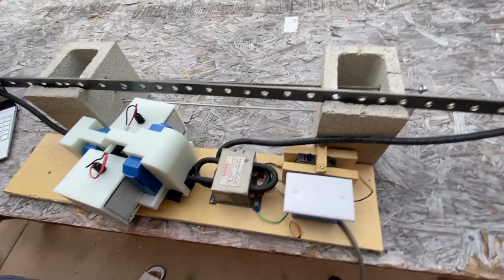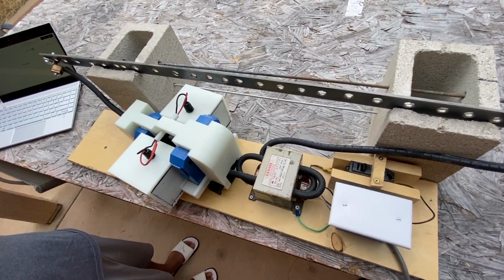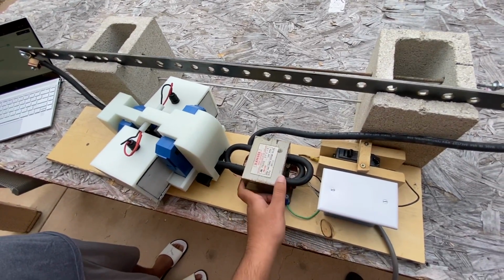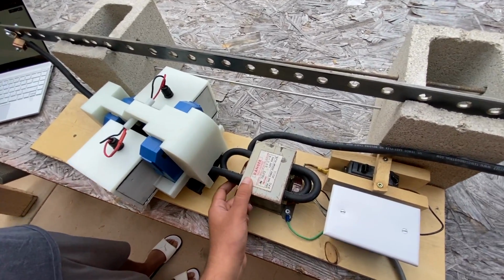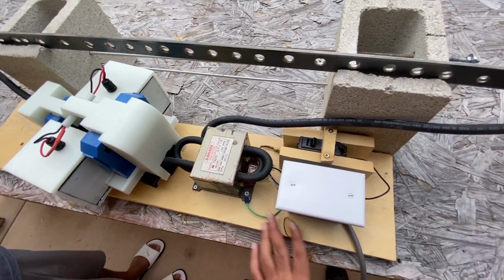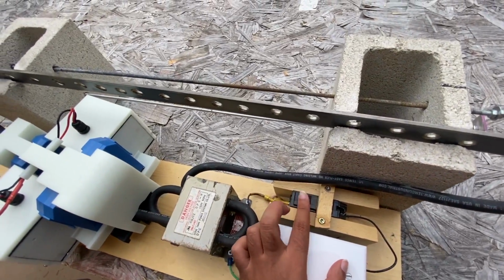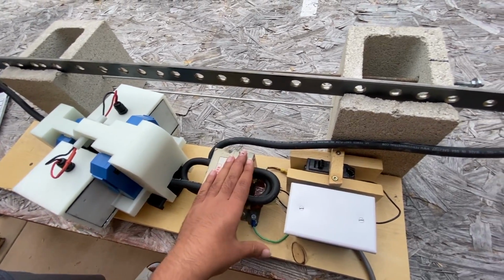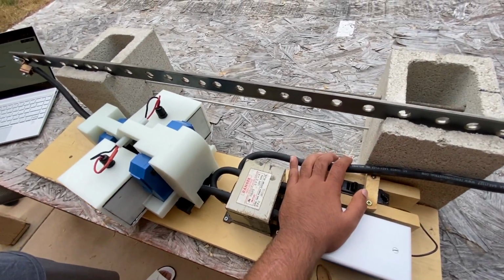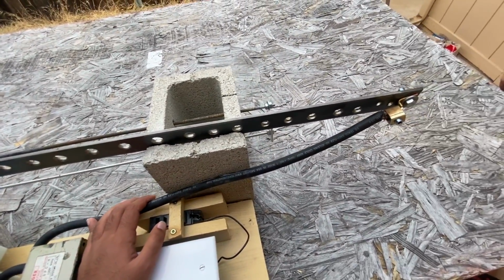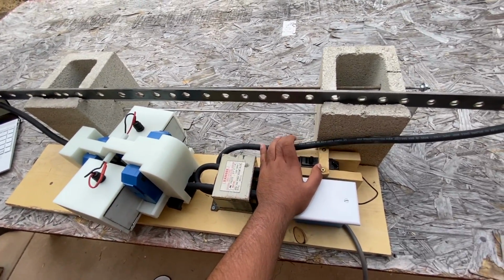Hello everybody, I'm going to give you a little overview on our testing setup. So basically we're using a step-down transformer to up the current so we can model distribution line currents. So 120 volt AC comes through here, through this breaker, and then to the transformer where it's stepped down to 2.3 volts. Because of this transformation, we're able to put out anywhere between 0 and around 1200 amps through this setup, which is useful for modeling distribution lines.